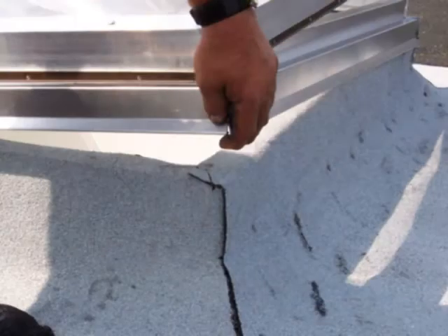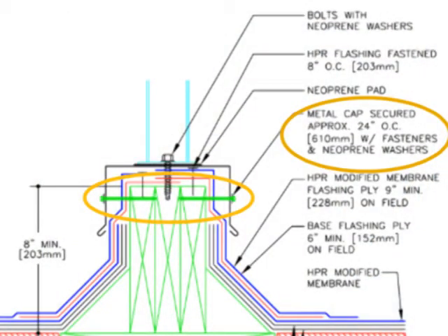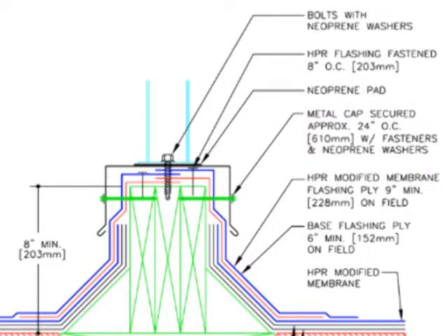Install pre-manufactured cover. Fasten sides at 24 inches on center with fasteners and neoprene washers. Furnish all joint cover laps with butyl tape between metal covers. Set equipment on neoprene pad and fasten as required by equipment manufacturer.